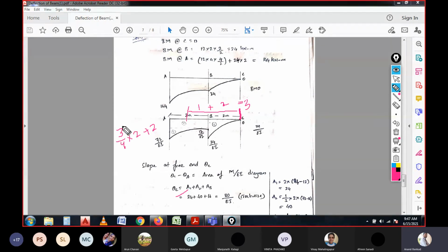And now the area of this is also the same 3/4 of the base, but here we don't have to consider the distance of 2 because it is considered from the C itself. So that is 3/4 of the base. So it will be 1.5, I think, correct? So that is how we need to calculate the CGs for each of the areas.